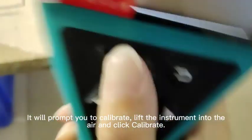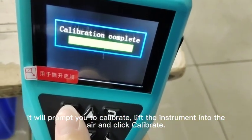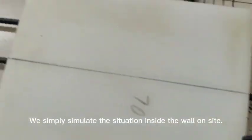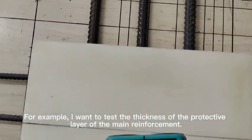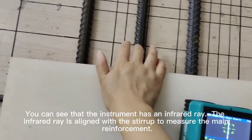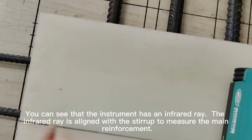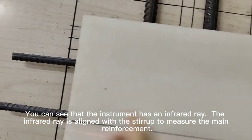It will prompt you to calibrate. Lift the instrument into the air and click Calibrate. We simply simulate the situation inside the wall on site. For example, I want to test the thickness of the protective layer of the main reinforcement. You can see that the instrument has an infrared ray. The infrared ray is aligned with the stirrup to measure the main reinforcement.